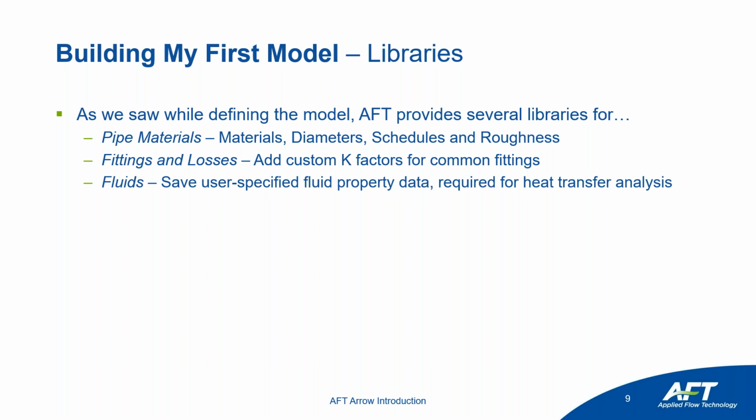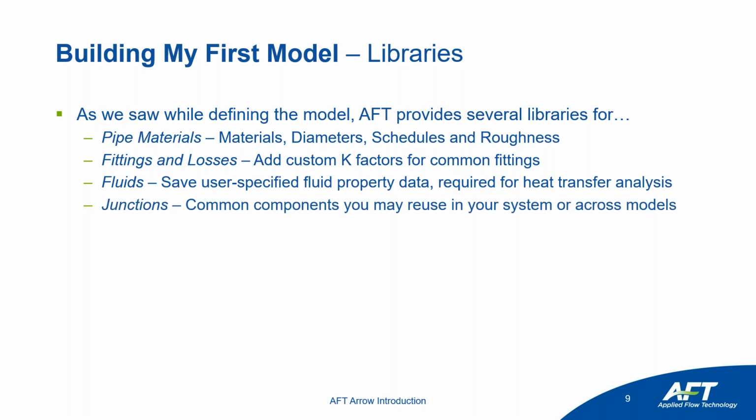Fluids, as we saw, we provide a few different databases, but again, you can save your own user-specified fluid database or fluid information that you can then call in different models, to capture your own distinct system. One thing we didn't touch on is how you can save junctions to a library. Let's say that we have a common valve that we're going to be constantly specifying or a common compressor we're using all the time. You can save that to a library. That makes it much more convenient to call in the future as you're building other models.